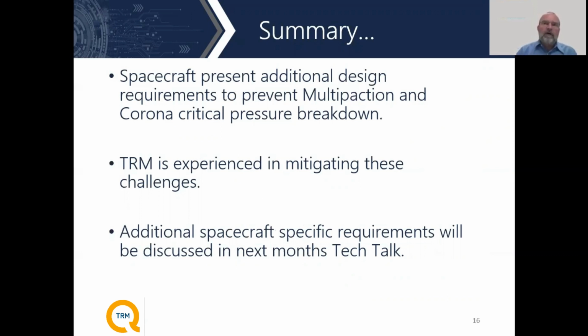Really, I think if you have a gap that is 30 mils or 50 mils across, you need a fairly low pressure to not have any molecules in that gap while the electrons are making that jump. So you don't need a full vacuum, but you need a reasonable vacuum. And I think that's something you just keep in mind as you're going through this. You don't need a perfect vacuum. You can have multipaction in a partial vacuum as well.